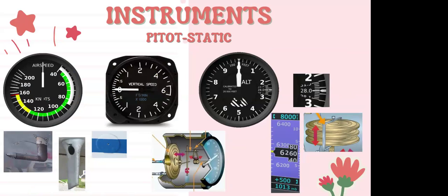our pitot-static instruments. Those are going to be our three remaining instruments, other than the three we just talked about, which are our airspeed indicator, our vertical speed indicator, and our altimeter. So when we say pitot-static, what do we mean? Well, we mean our pitot tube and our static port. Now, that's the case in the 150, where we have those two separate areas to get that information, pitot tube, static port.